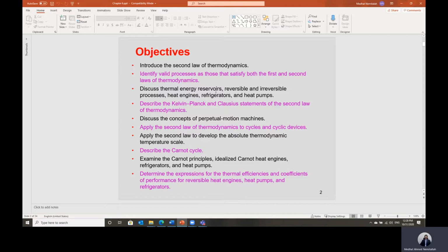The other main application is the refrigeration and air conditioning system and also the heat pump system. All of these systems work on the same cycle, based on the principle of converting work into heat, not heat into work. So in the case of refrigeration and air conditioning, we cool down a medium by absorbing heat inside the evaporator, and then we reject the heat inside the condenser.